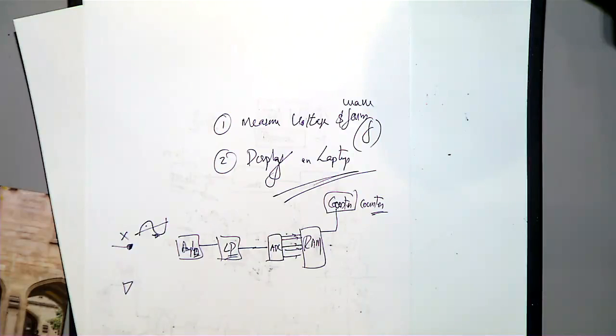In the RAM, if your digital data is simply coming in and storing, later it is not possible to retrieve it. So you need to store it properly with some digital address. That digital address is generated by a counter. We will study this in detail later, but this is just an end-to-end overview. That is the reason we need a counter. Whenever you have a RAM, you need to generate some address, and with respect to that address we store the data in the RAM.